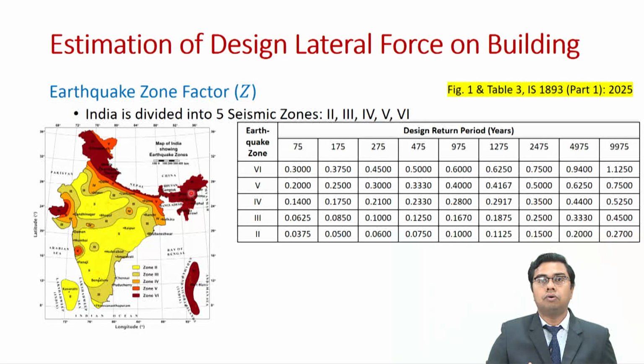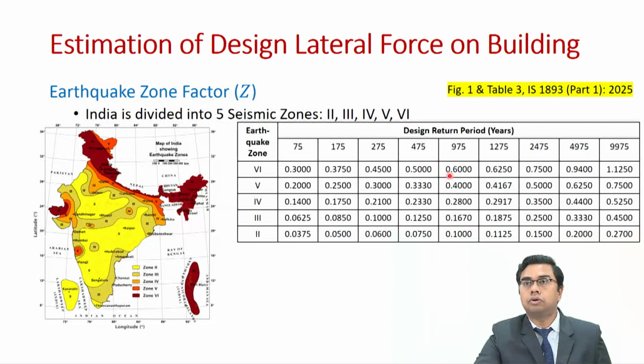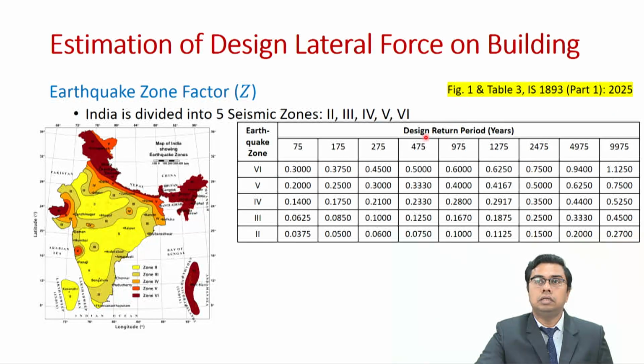So based on the location of the construction and the design return period of the earthquake, which is considered in the seismic design, we will have the value of earthquake zone factor. These values are shown over here and are adapted from table 3 of IS 1893 part 1 2025 version. So here you shall be able to see that this is based on design return period. We have looked into